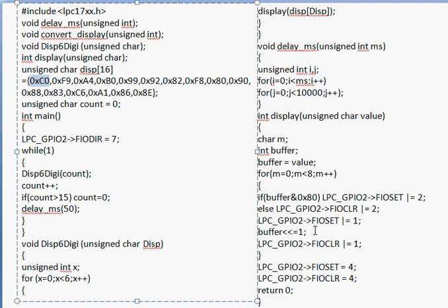Then we shift it. Now C0 you have, once you use this, buffer is equal to buffer shifted by 1 bit. So 1 bit you shift towards left. So 1100 followed by 0000, that is C0, becomes 80. Is it correct? Because the 1 goes to the carry, and the bit next to the MSB goes to the MSB position, so you have indeed 8.